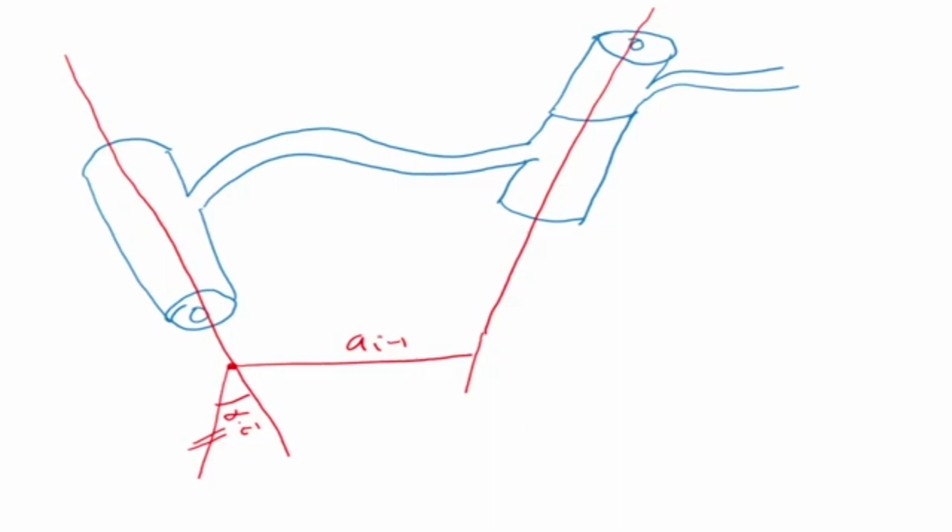Now let us fix our xyz axes of the frames. So this axis is what we call my z frame. So I put my z axis like this. Let me put some other color and say that this is my z axis. Okay, along this is my z axis, so that is z_{i-1}. Now x_{i-1} is along this perpendicular distance, so this is x_{i-1}. And what about y? As per the right hand rule, it is that side, y_{i-1}.